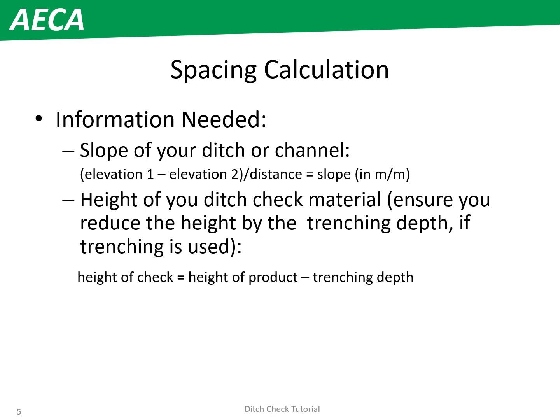Ditch check spacing calculation. It can often be left up to the crews in the field to determine how far apart to place the ditch checks. But as an erosion and sediment control designer, you really should specify the ditch check spacing on your erosion and sediment control measures drawing to ensure that the ditch checks function properly, as well as to ensure that sufficient ditch check supplies are brought to site.